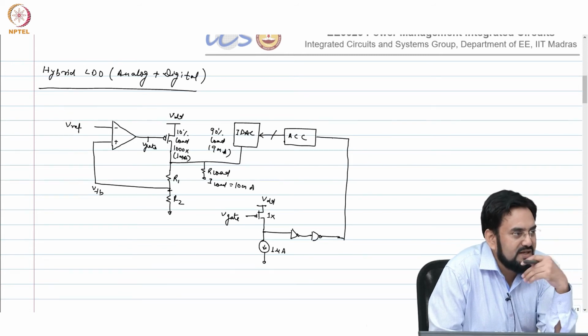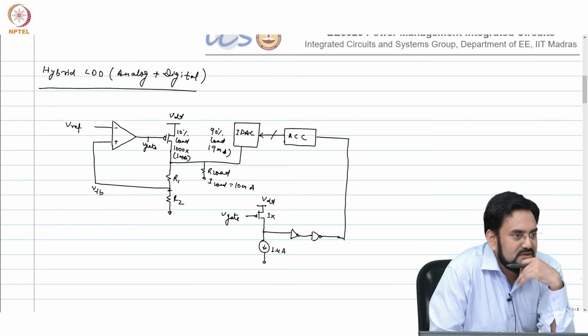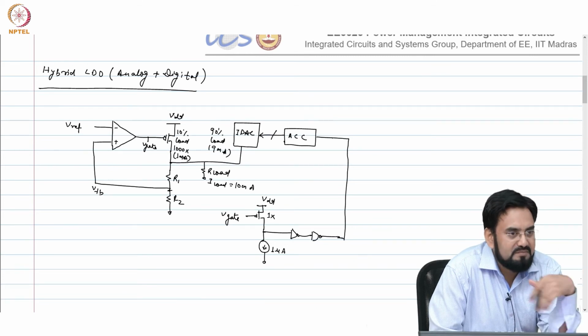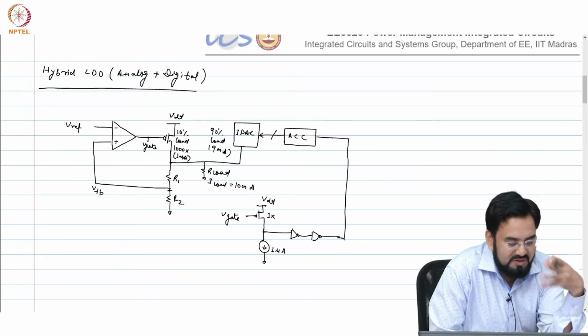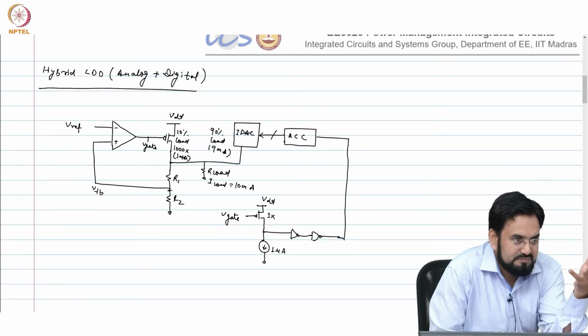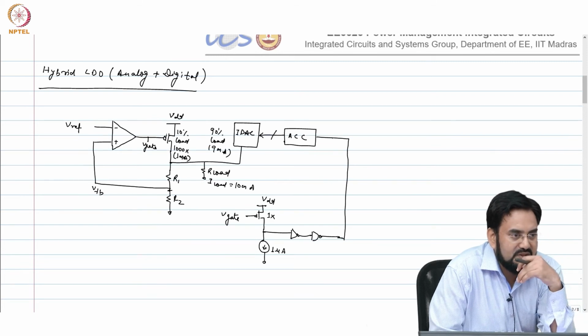So your current will go 100 times. So instead of 1 milliamp, it will start drawing 100 milliamp. So surely it will damage your device and it will melt your pads, everything actually, because those pads and your metal lines, everything is not sized to carry that. Even if you keep 5x, 10x margin, it's still 100 milliamp, much higher.